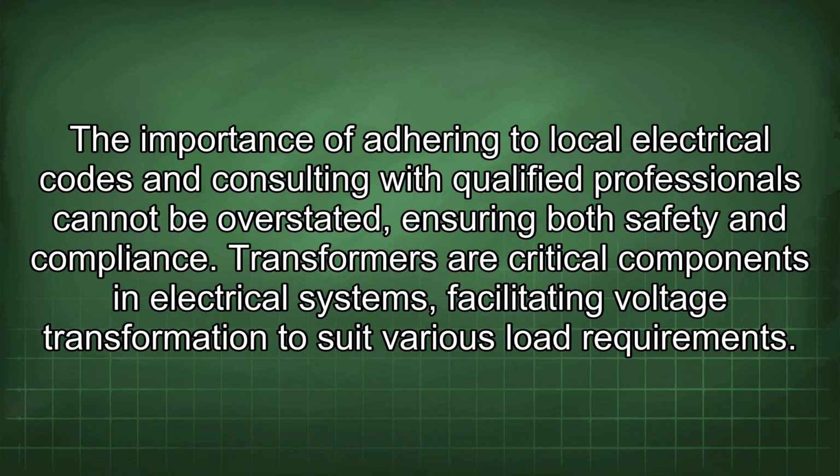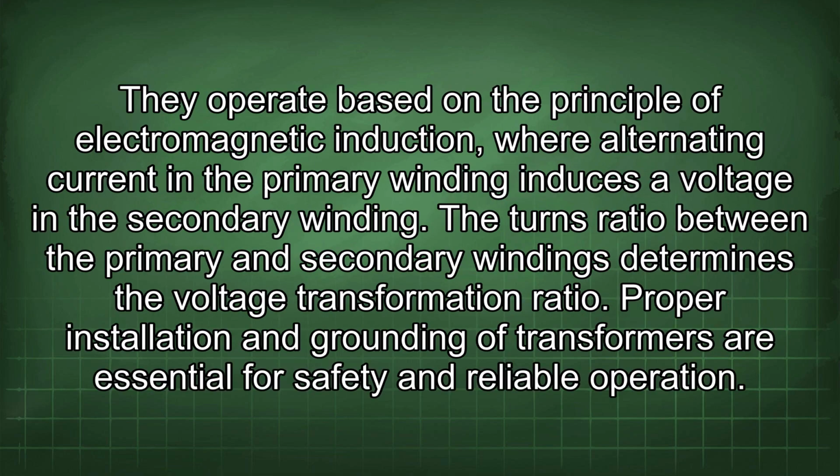Transformers are critical components in electrical systems, facilitating voltage transformation to suit various load requirements. They operate based on the principle of electromagnetic induction, where alternating current in the primary winding induces a voltage in the secondary winding. The turns ratio between the primary and secondary windings determines the voltage transformation ratio. Proper installation and grounding of transformers are essential for safety and reliable operation.